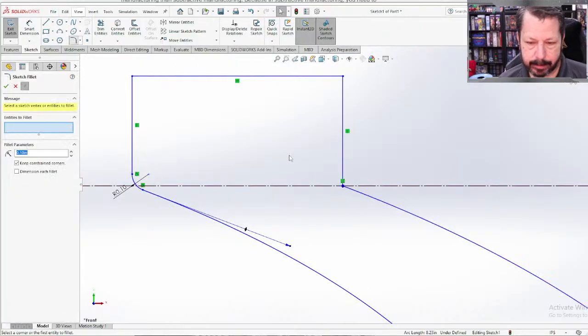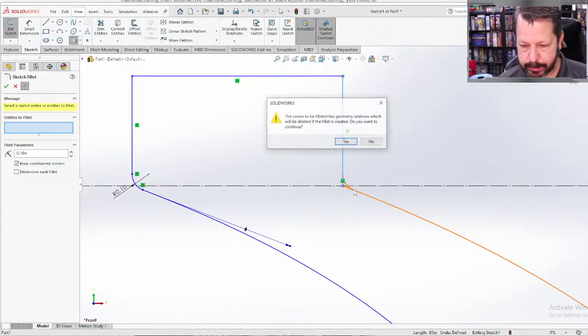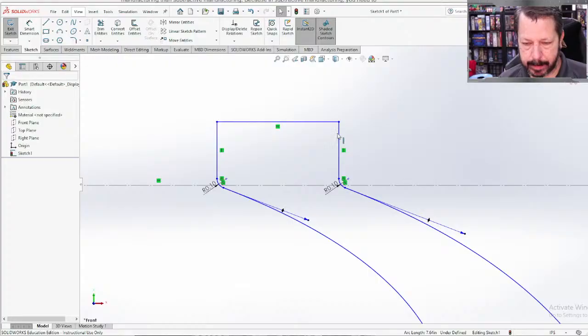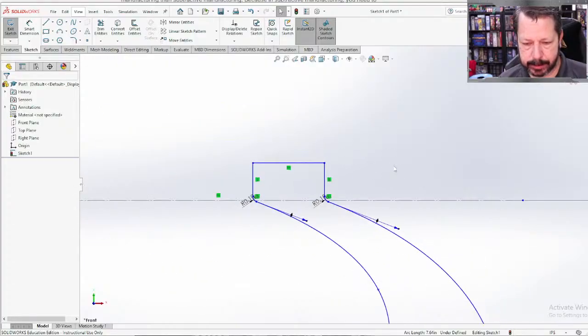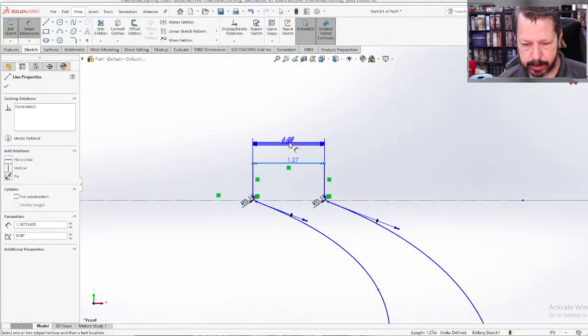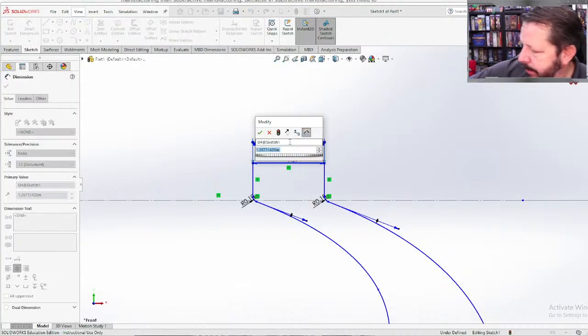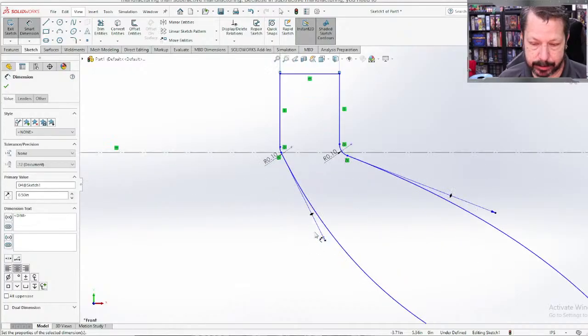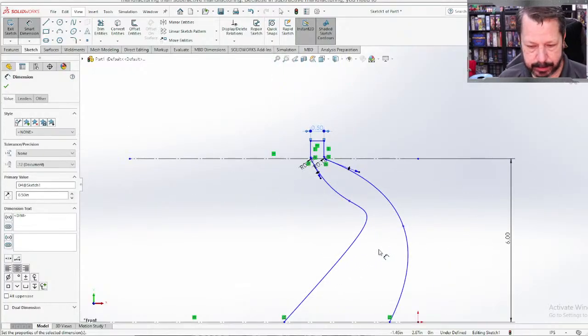Really doesn't like doing all these things at once. Same thing there. It's going to delete the right angle. The top we'll leave squared off, but let's dimension that. If that's going to interface with our plane, that needs to be maybe a 1/2 inch, and that cavity is actually pretty deep in there. So let's make this 0.5 inches.